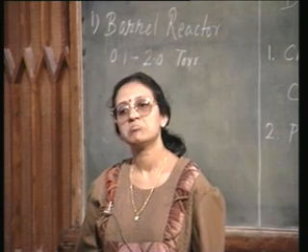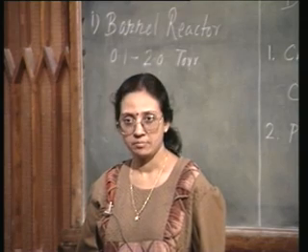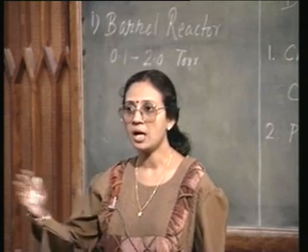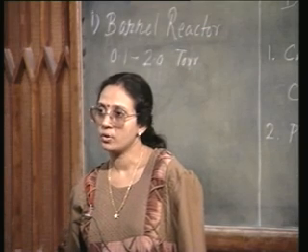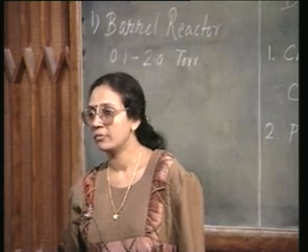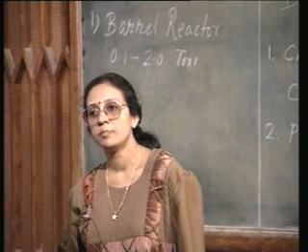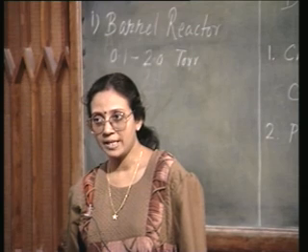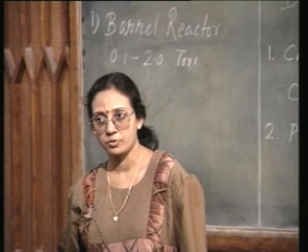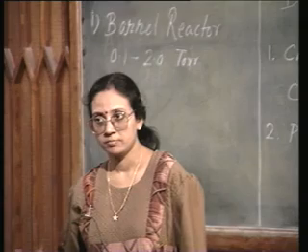Pressure is also comparatively high, 0.1 to 2 torr, it is on the higher side. So, ion bombardment energy is going to be quite minimal. Therefore, the etching is going to be purely by chemical means. So, the etch profile is going to be isotropic.